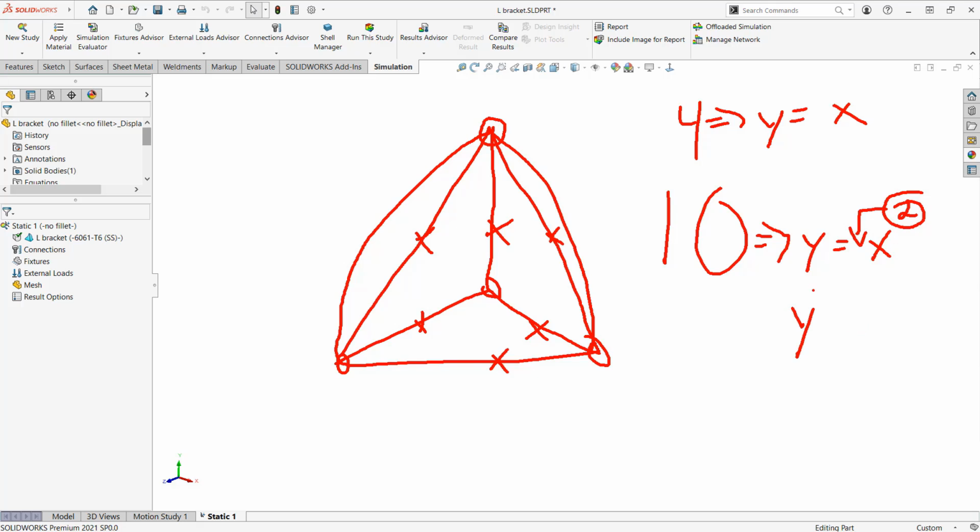So then it becomes the first derivative, a linear derivative, or this then becomes a constant. So when you do this calculus operation, which is going on behind the scenes, whether you like it or not, you're going to get a definition here in the stress as being a linear stress field or a constant stress field throughout the element.